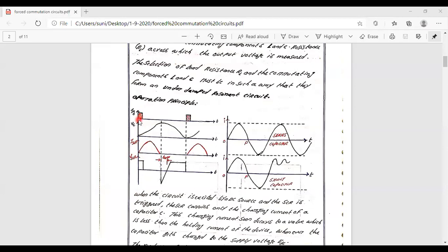Here, considering these waveforms, as you know, the gate signal is provided for a minimum time. Why is it chosen to be minimum? It is to reduce the gate circuit losses. You may continue this gate signal up to this instant, but the gate signal required by the device is short, and it should be in this particular manner. If it is a continuous signal, there is no use of providing the gate signal all the time, in spite of having much gate power loss.